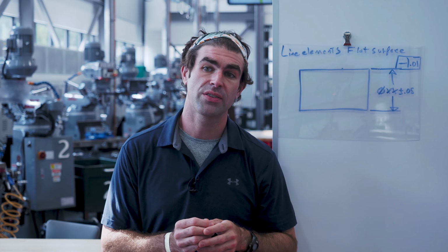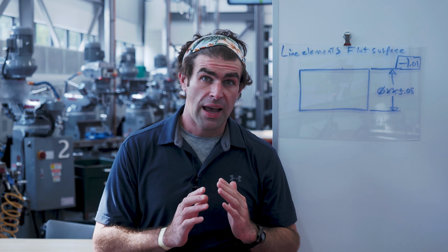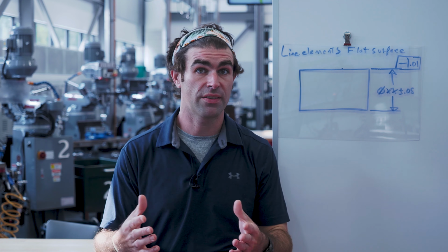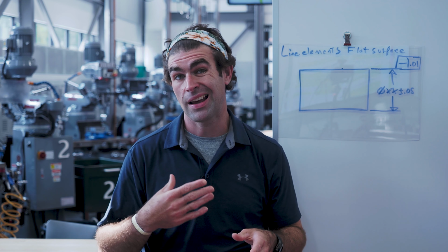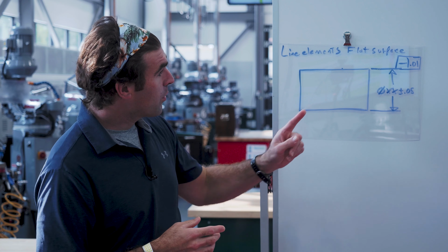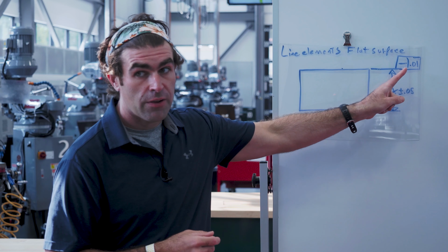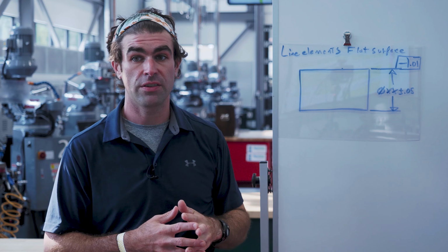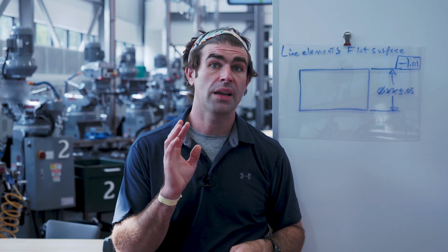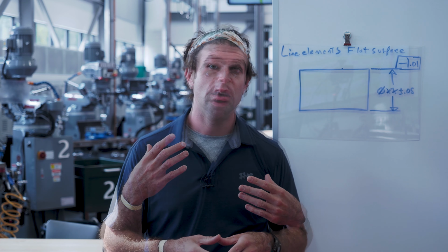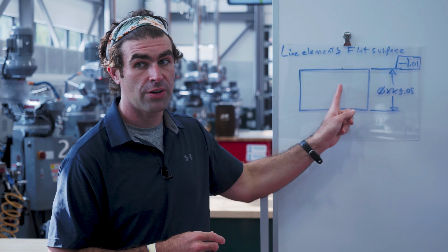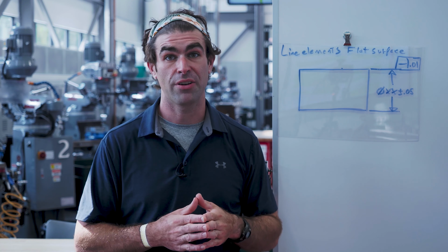So with all of these, it's important to see how the feature control frame is connected to the orthographic view, because it does matter as to what tolerance applies, how you make it, and how you inspect it, okay? So if you've got a straightness tolerance that's on the extension line or on a leader line pointed to the surface, it's applying to the 2 parallel lines on this top surface in the direction indicated by the orthographic view.